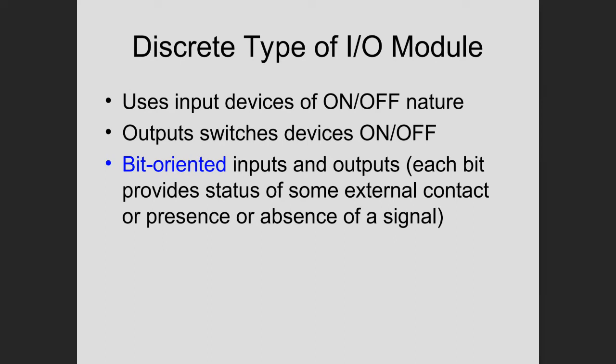Anything that you can think of that can be described as being in one state or another, not a set of continuous states, but one state or another, that's what we mean by discrete. And most of the time when you're dealing with these PLCs, you're going to be using discrete I/O. Not all the time, but most of the time, by far, it will be discrete.